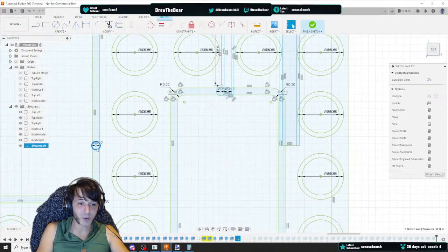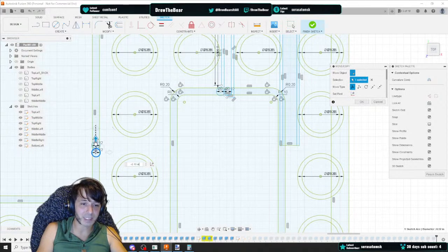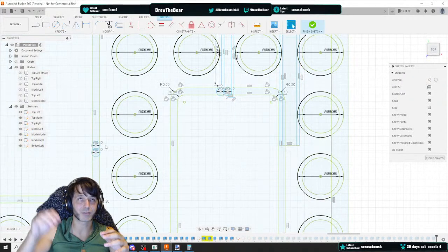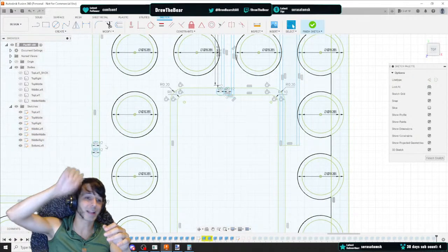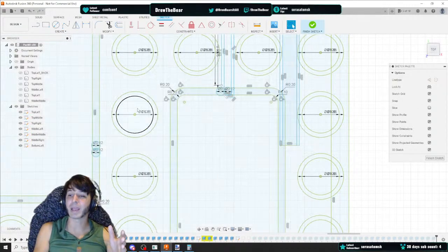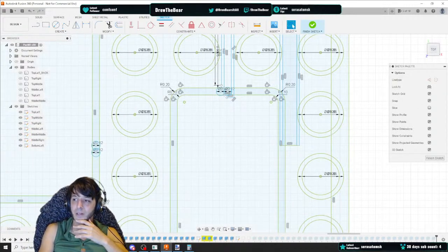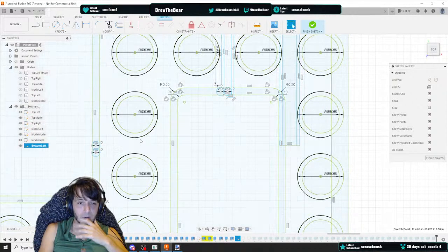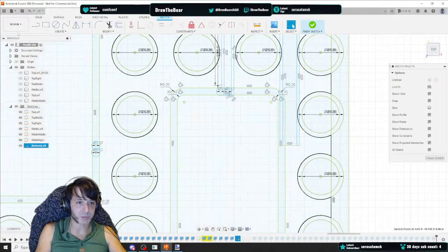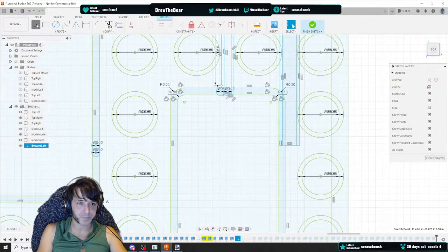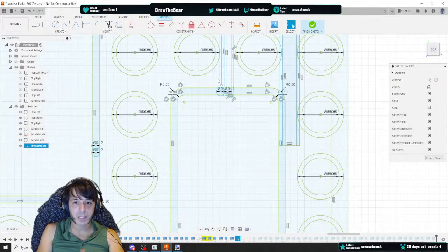And then I'm going to create another one. Even though it doesn't go anywhere after this, I want to create another one because I want a place for the L wire to go up and then back down again so it can be hidden, whatever's remaining of the L wire. So that should be correct, and they're at the right height. They're at 0.9. So now we just need to create the lines between them. These are the right height? Yes, 1.15. Got it. Okay. Get rid of these constraints.